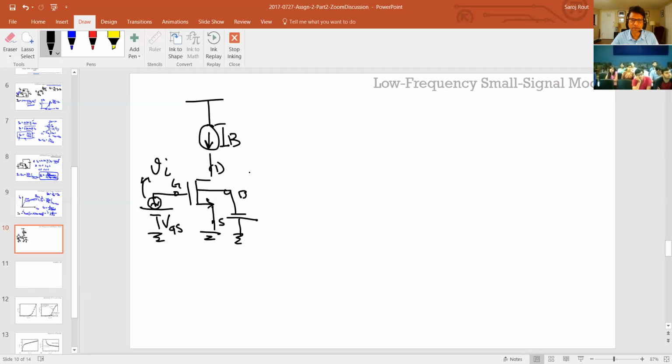Okay, so if I want to construct the small signal model for this, and the reason I want to do small signal is, let's say I want to find the gain, right? So let's say that's your small signal output, and you've been writing the self gain in problems here, which is nothing but this V naught over VI when you bias it in this fashion. Here it's called self gain because the output impedance of this element here is infinite, right? So we're just taking an ideal current source. The R naught for this is infinite.